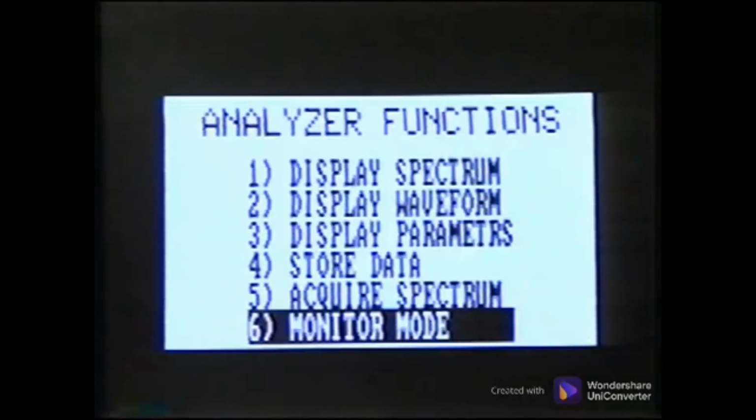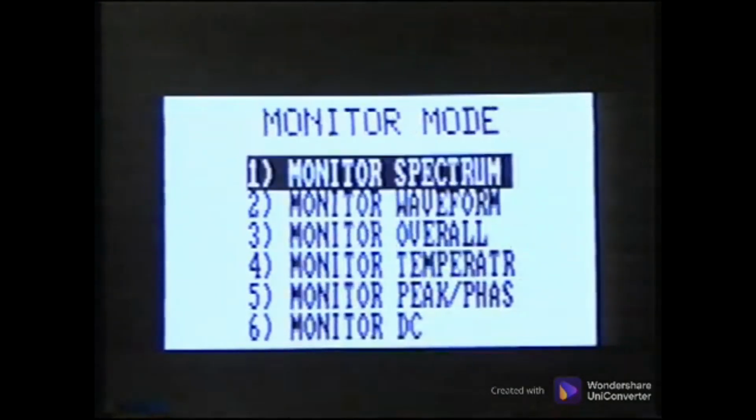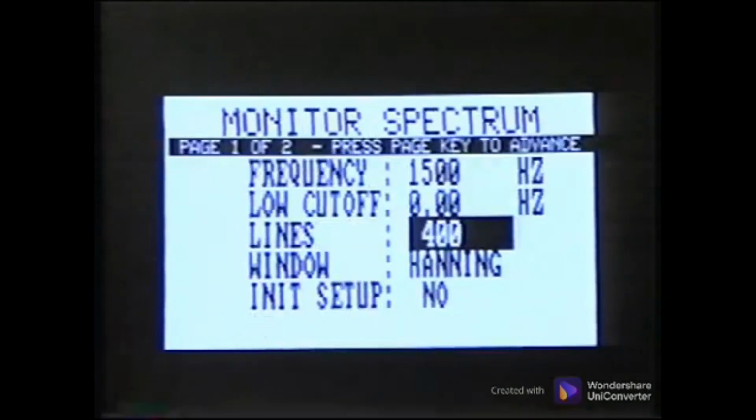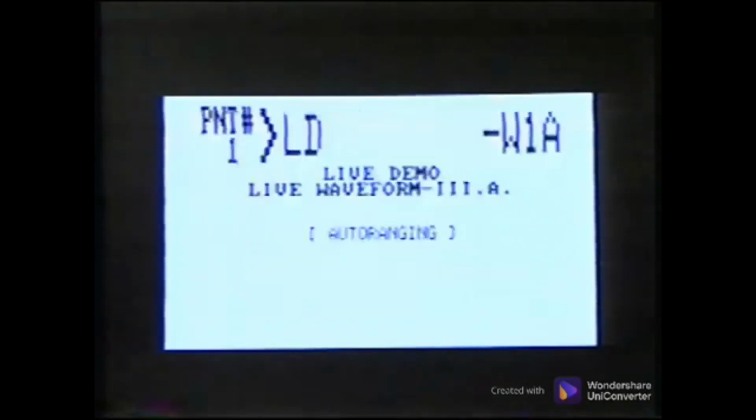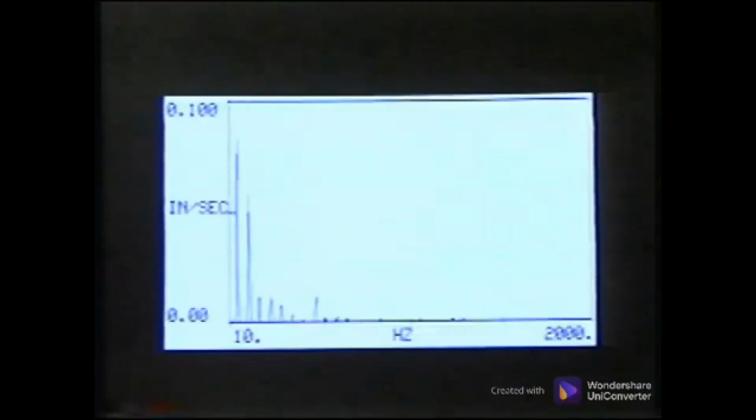When the coast down is monitored in the spectrum, the data is only as good as the update rate of the analyzer. In other words, as the waveform is sampled, the process time to perform the FFT and display the spectrum may cause the actual shutoff event to be missed. While the machine is running with a load, there is some fluctuation in the signal. Without adequate resolution, the multiple frequencies may appear as one, and the drop-off due to electrical energy may not be as noticeable.